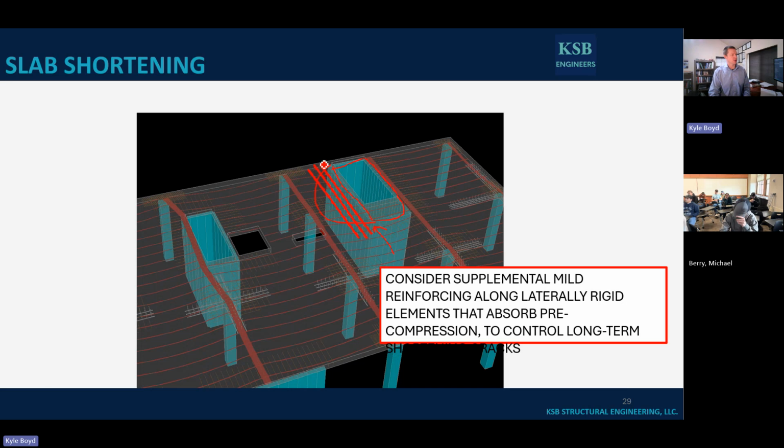So what am I going to do? I'm going to throw a couple pieces of rebar alongside that concrete core wall right there to make sure that that happens. And I learned this lesson the hard way. We were doing a building multiple stories underground, and it was up on like, I don't know, level 5 or level 6. Somebody was moving in with a U-Haul, knocked the sprinkler head, and started flooding this region right here. Well, this crack, we didn't have this bar in here, so we had pretty good crack right here. And it happened at every single level for the next 5 levels going all the way down.